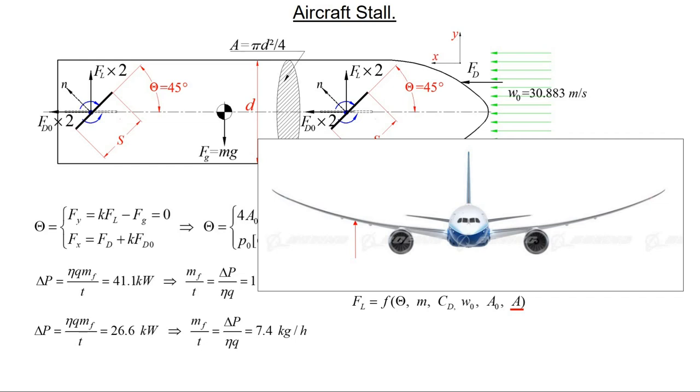For wide-body fuselage planes, weight is the biggest enemy, which increases petrol consumption, which means cost of tickets and a lot of CO2 and heat released into the atmosphere per passenger. Aviation-grade aluminium is well-established material, yet it is heavy compared to carbon fiber or fiberglass. On the other hand, it is well-tested material in aviation. New material usage in aviation requires a lot of research and development and a lot of time on site testing.